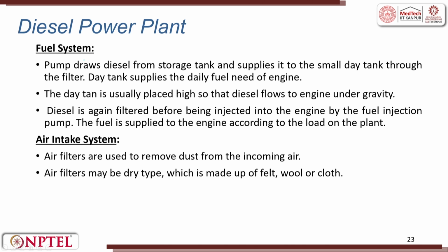Then the fuel system. The pump draws diesel from the storage tank and supplies it to a small day tank through the filter. So you have a large tank, you send it to a smaller tank. From the day tank, it is then sent to the filter. The day tank supplies the daily fuel need for the engine, because you might have a larger tank and then a smaller tank. The day tank is usually placed high so that the diesel flows to the engine under gravity.